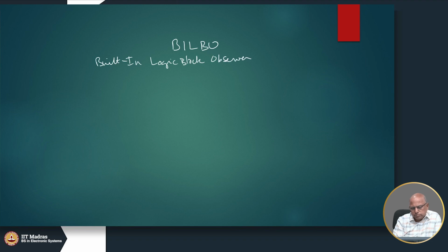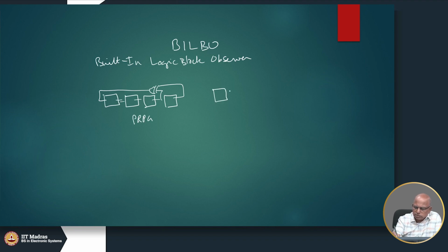Remember what an LFSR is. Okay, what is an LFSR? This is an LFSR or a PRPG. So this is PRPG. If you use it as a shift register, it will look like this. So this is our serial input, serial output. This is a shift register.